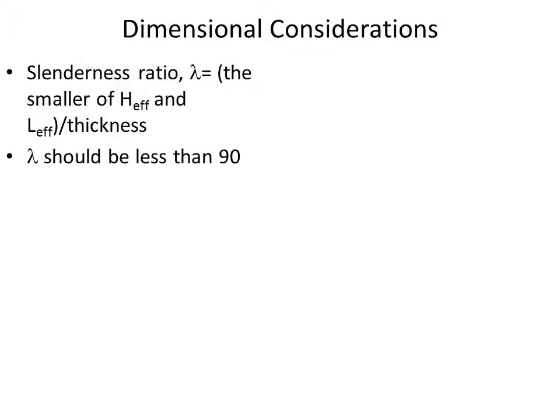But in most of the masonry walls you will be facing, designed typically at a height of 3 to 4 meters or so, you will not have an issue with slenderness. Even if it is 5 meters divided by 0.25, that is 20.